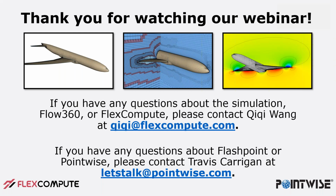Can Flashpoint handle geometry change? Yes. When you set up Flashpoint surface meshing for the first time, if you don't tweak anything, then that's basically out of the box. Just bring in a new geometry, and you can even push the button on the toolbar that says Flashpoint automatic surface mesh. You just push the button on the toolbar and it'll create a surface mesh.